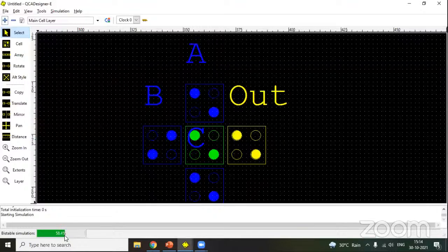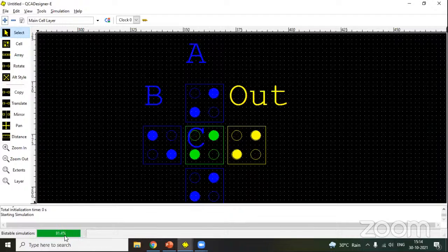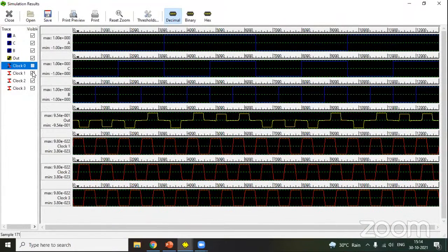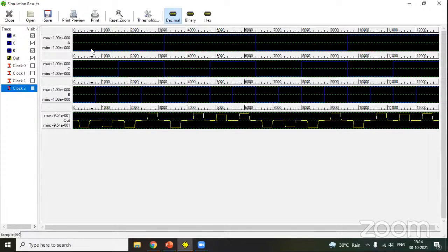We will see the simulation waveform. If A is fixed and we change B and C, then based on that the decision will change. We are giving 1000 iterations now, so it is taking more time. And at the bottom, see, this is the output waveform. So A is 0. Zero means it is working as an AND gate. We fix one input, then the remaining two inputs decide the output, and the majority gate works as an AND gate. So 0 0 0, 0 1 0, 1 0 0, and 1 1 output should be 1. So this works as an AND gate.